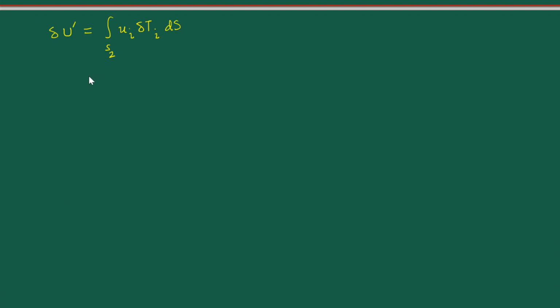What we have to just do is one little step where we realize that now because we are considering the part of the surface S2, there it is the displacement boundary conditions which are specified to us. So the displacements are given to us, which means that again over that delta ui is equal to 0. Okay, so we can very well take this ui within this delta operator.